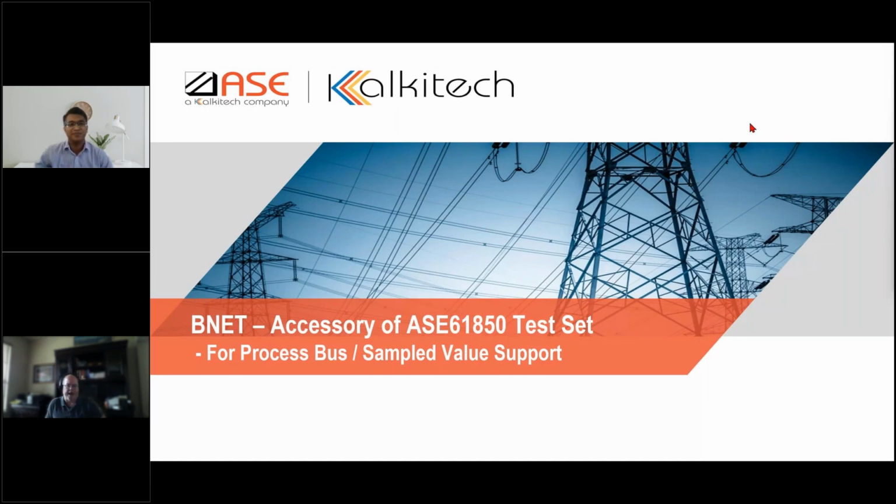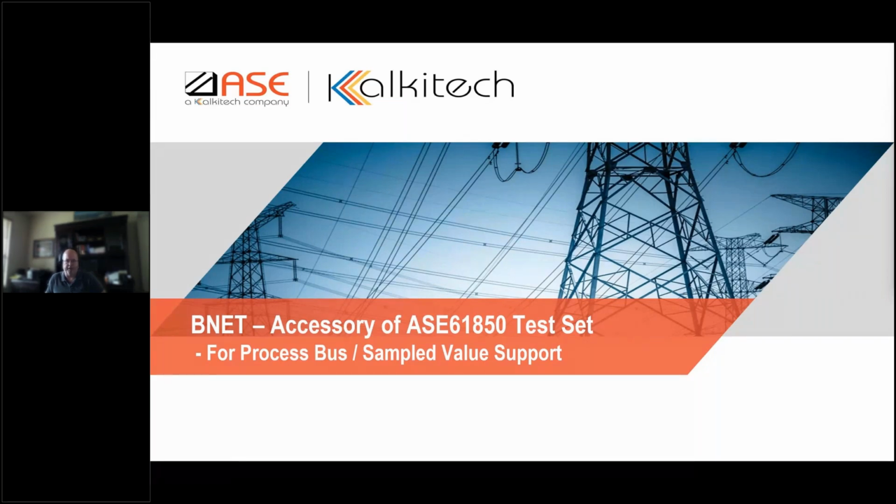So I come from a background where DNP3, Modbus, and other protocols in North America are prevalent, using the ASE2000 test set. Why haven't we incorporated any of the 61850 features into the BCOM unit accessory that goes with the ASE2000 test set? Mainly the processing requirement of process bus is on a higher side compared to any other station bus protocol.